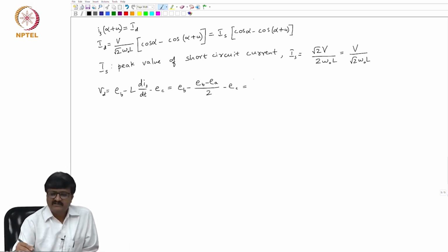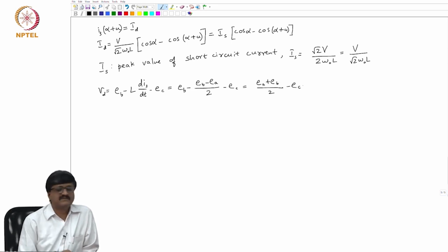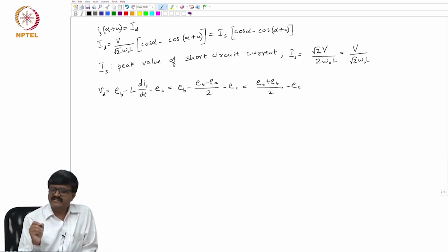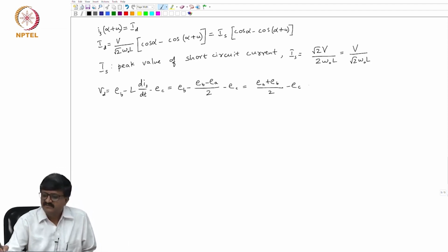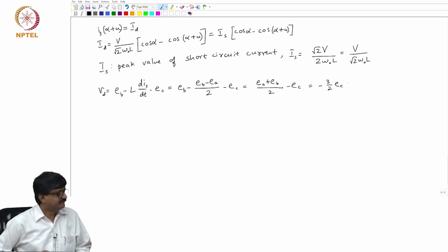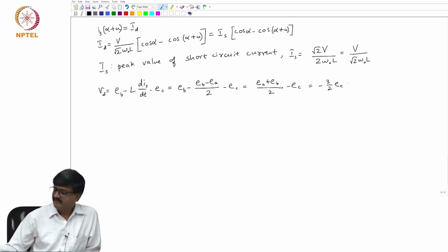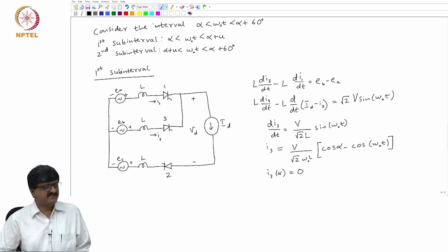So, EB minus EB by 2 is EB by 2. So, I have EA plus EB by 2 minus EC. Now, EA, EB and EC are balanced. So, that means EA plus EB plus EC is 0. So, EA plus EB is minus EC. So, this is equal to minus 3 by 2 EC. So, this is the expression for Vd in the first subinterval.